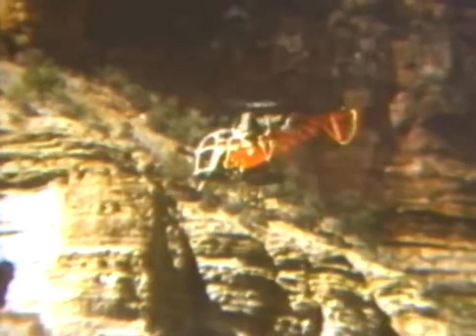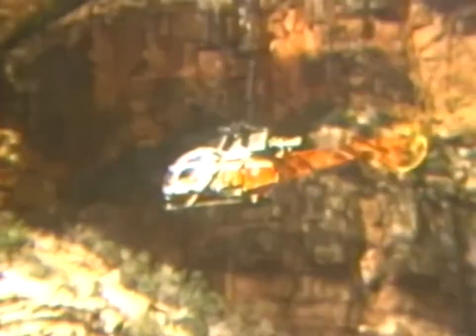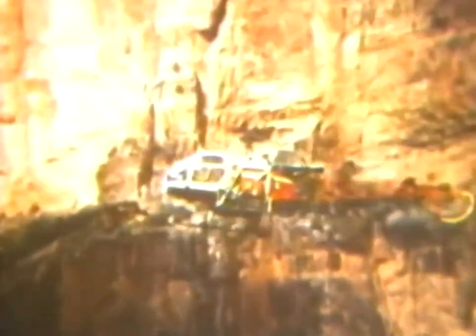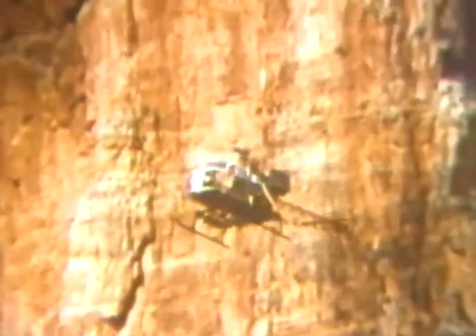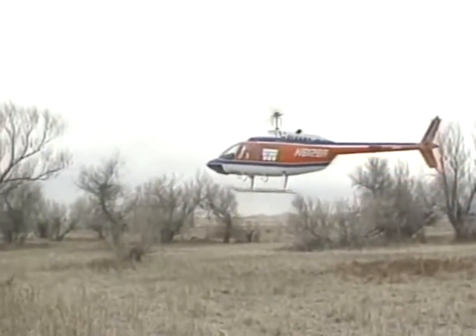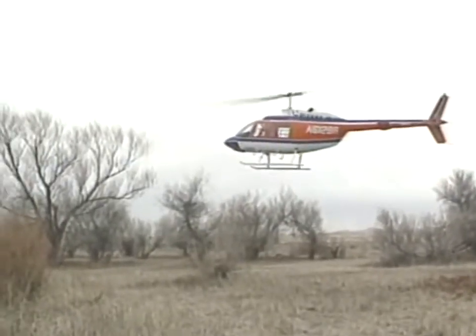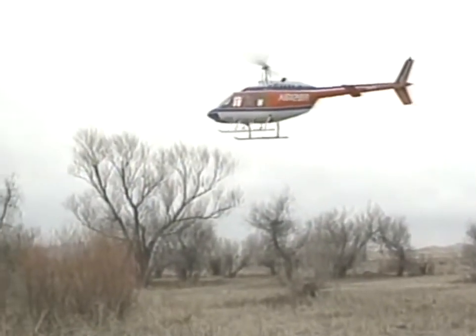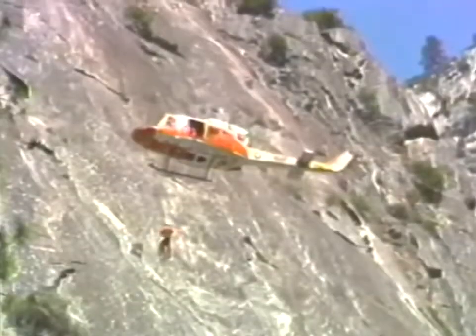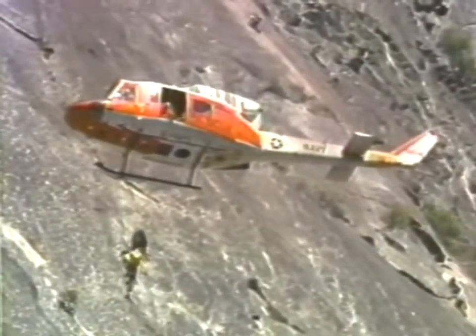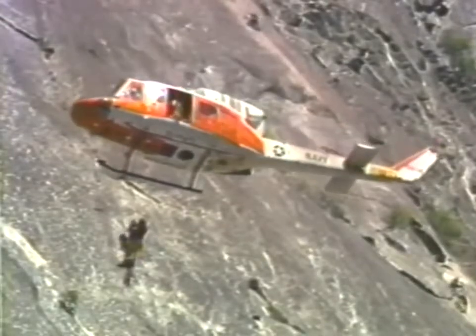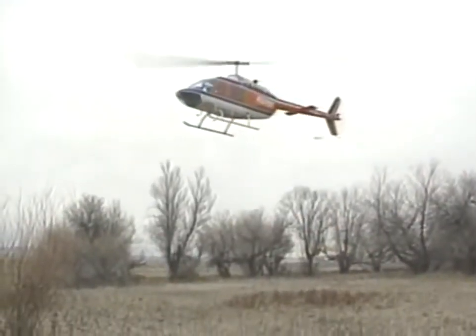When the helicopter must hover out of ground effect, HOGE, to enter or leave a confined area, or to clear a tall obstacle without the benefit of translational lift, this is called a maximum performance takeoff or landing. During this maneuver, the helicopter is totally power dependent and margins of safety are reduced. So whenever possible, try and avoid these types of landing areas.